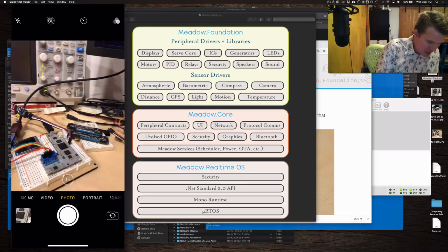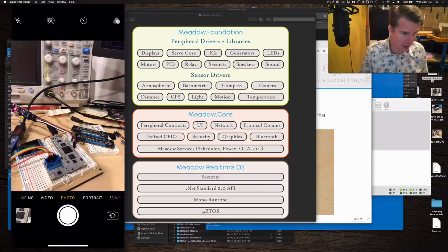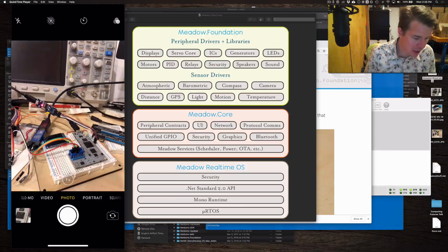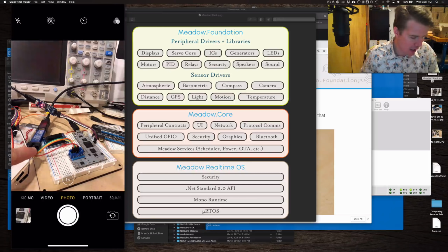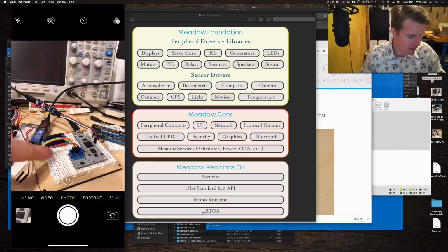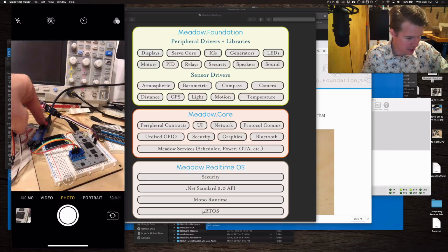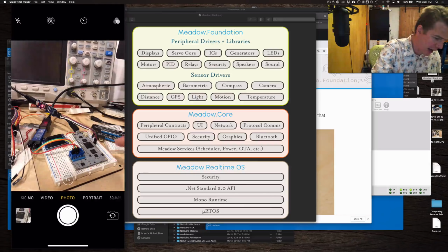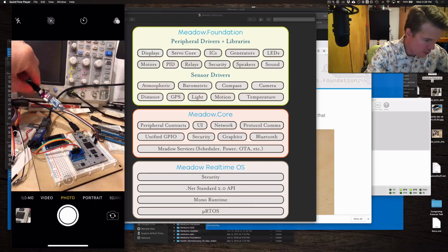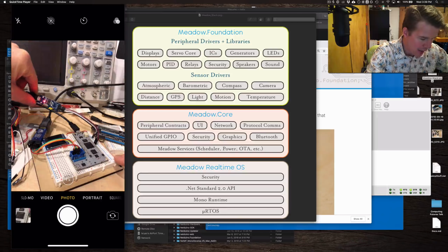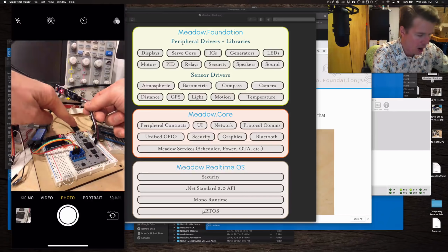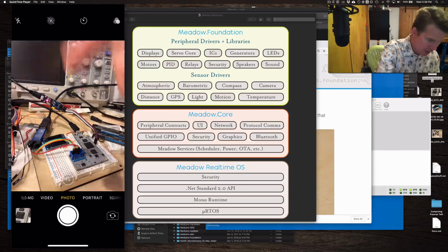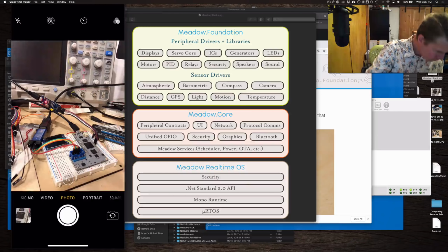So here is that debug board fully wired up, and it looks like a patient in a hospital, some sort of Frankenstein electronic patient. Coming off of it, we have a JTAG. So this is a JTAG header, and this is a JTAG adapter. So this is USB to JTAG. And then over here we have a serial to USB board. And then we have the regular plug-in, so this is where we get USB power, and this is where we can do some DFU flashing and stuff. I'll tell you about that in a moment.